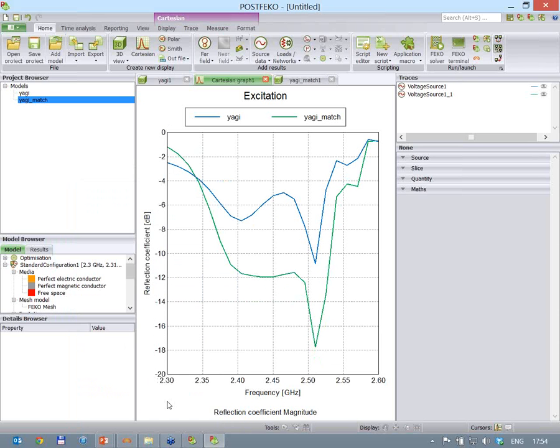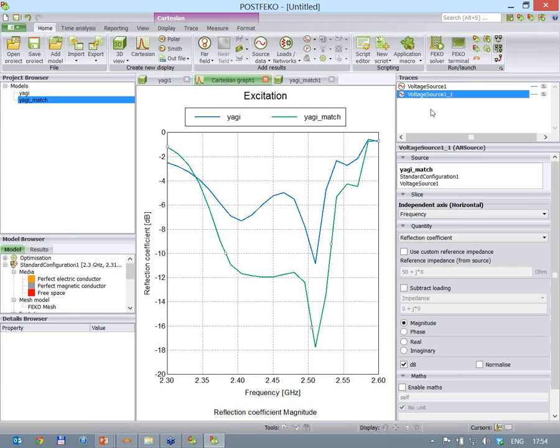As soon as that's set up, you can see very intuitively and easily that between 2.4 and 2.5 gigahertz, we definitely now adhere to our required -10 dB match. It's very easy to get some specifics on this particular trace that we are now measuring.